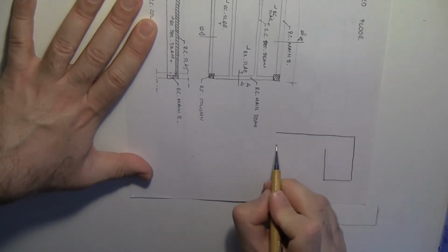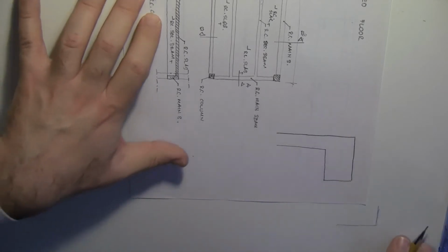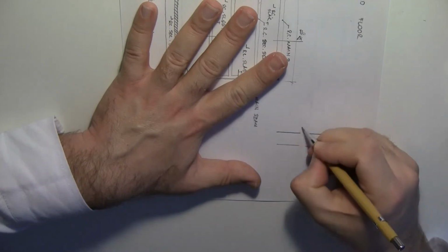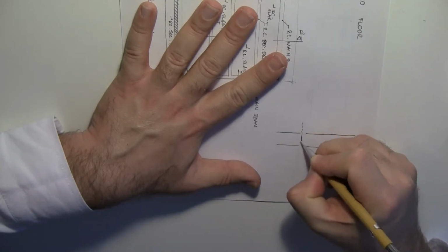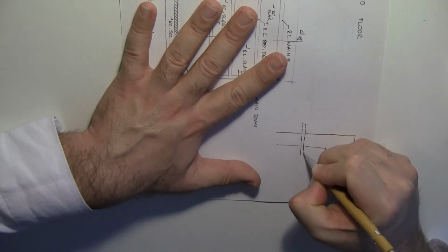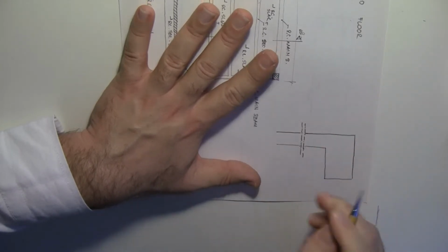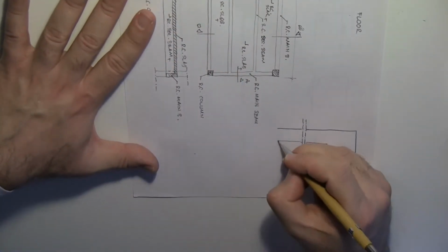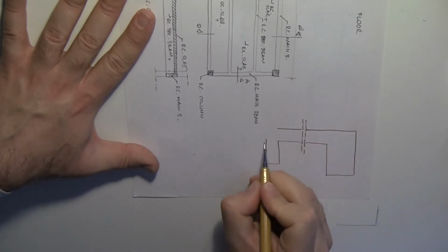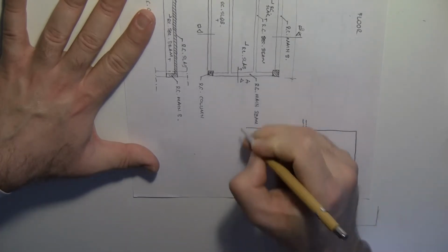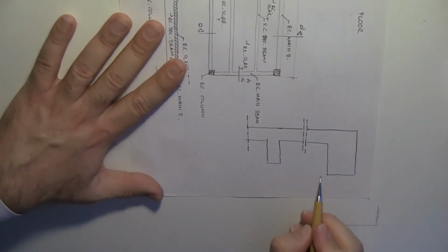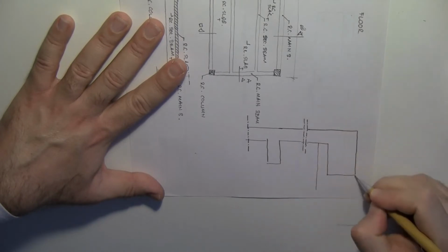Okay, and I will go like this. And I will do something. I'm going to erase this part. And I'm going to put two dashed and dotted lines very close to each other in order to represent that. I cut some part out of there because I want to fit my drawing here. That's what we architects do in order to fit some large drawings into small spaces. Whenever something continues, we can just cut some parts of it.